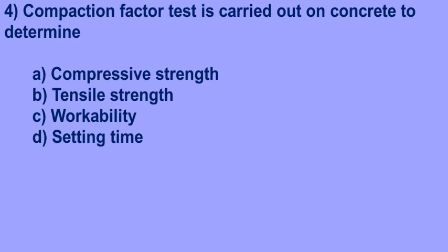See here, a cylinder concrete specimen of 150 mm diameter and 300 mm length is placed in the apparatus, and a compressive load is applied uniformly until the concrete splits. A metal strip is placed above the concrete specimen to ensure a uniform distribution of the compressive load to the concrete sample. The compressive load at the time of splitting is measured and recorded. Tensile strength of concrete can be calculated using the formula 2P divided by pi DL, where P is the compressive load at the failure, D is the diameter of the specimen, L is the length of the specimen.